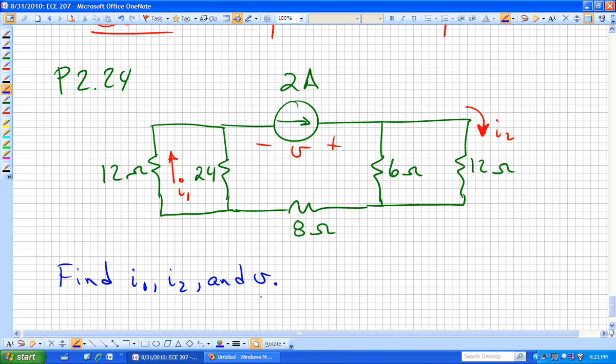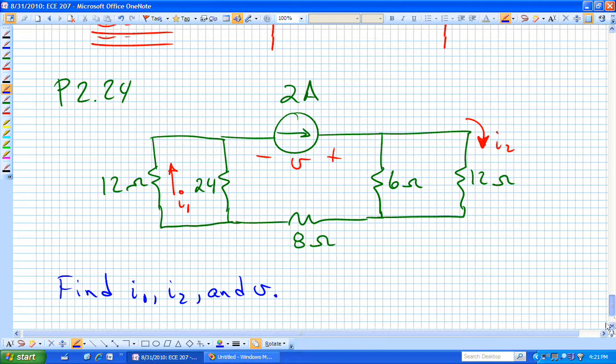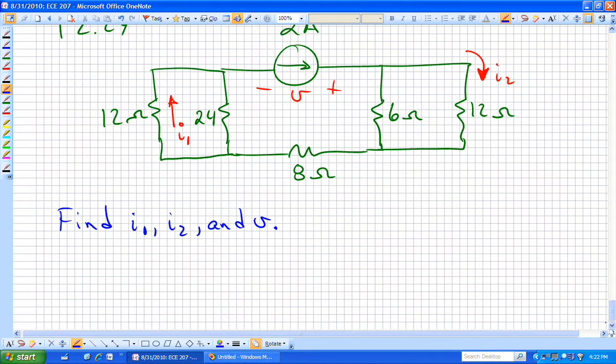And if we know the resistance and the current, we can find the voltage, and that will give us our voltage dropped across that source. That's the concept. Once we have the voltage dropped across there, we can start pulling our way out from that condensed circuit. Let's start by combining